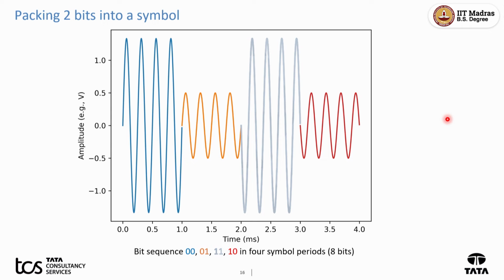The transmitter must help the receiver. The receiver cannot do it if the transmitter doesn't cooperate. If you ask the transmitter to send 011110, the transmitter will automatically prefix that 00 and send it. The transmitter won't tell you it's doing that, but it will add that 00. If you say I want this sequence 00011110, the transmitter will still add one more 00. It will always do that. Both transmitter and receiver will use that and ignore it. The receiver will not give that first 00 to the consumer of the data. Whoever needs those bits will not use that 00. That will be between transmitter and receiver.